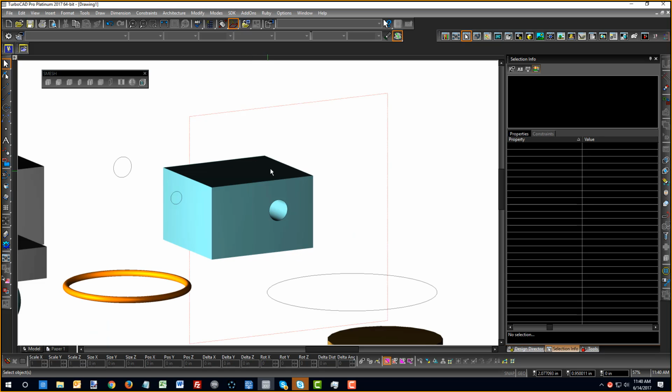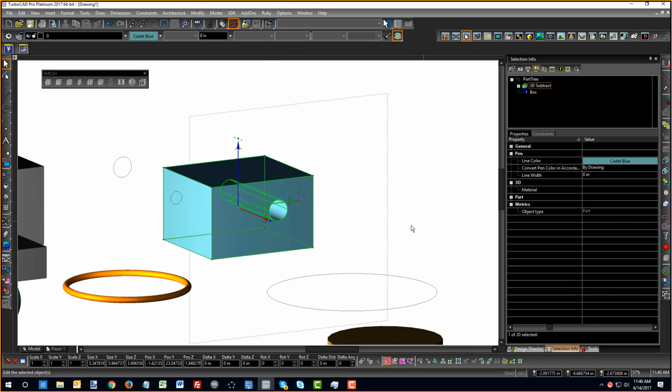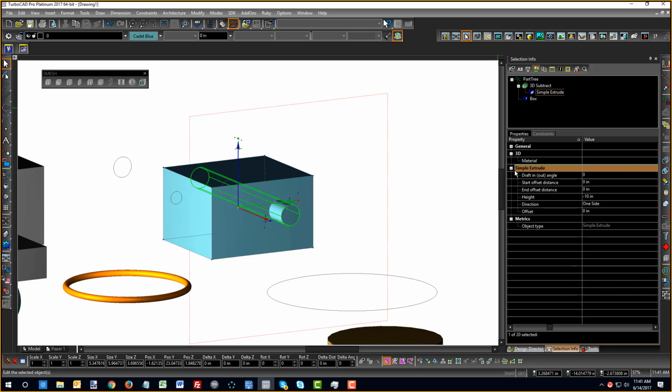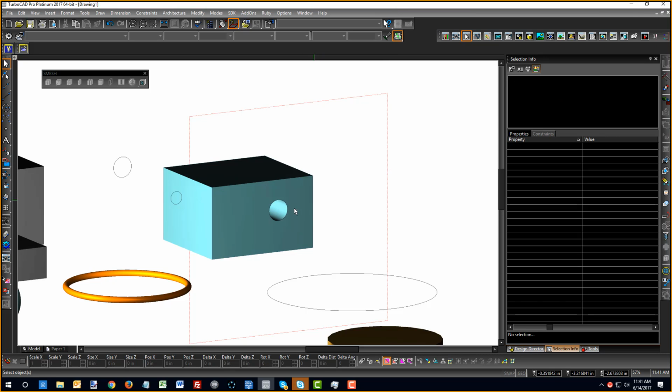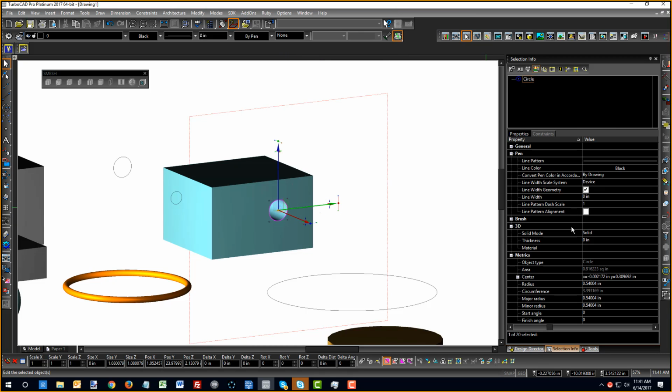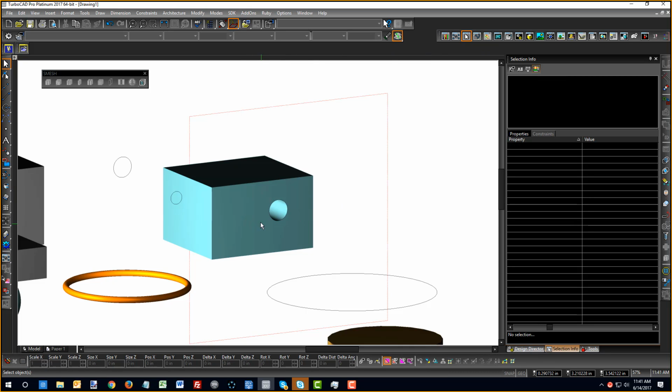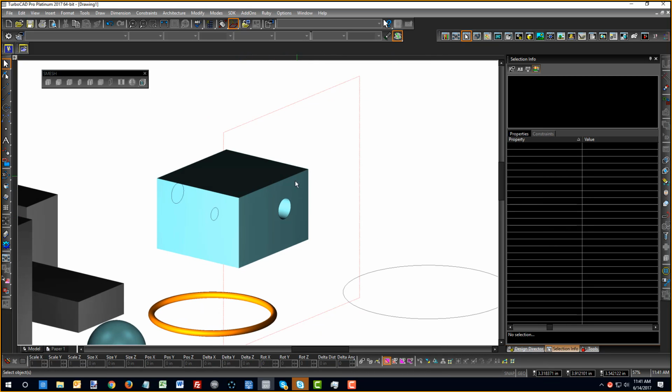When working in TurboCAD, the reason that's important is because now, even though I've done my 3D Boolean here, I can go to any of the objects in that and change that. So if we just look at this here, in fact, if I go to the circle here. Normally you could leave that on the face, both faces. I've seen times where it gets a little bit funky in that you'll go somewhere down the line and you'll get some faceting stuff occurring.